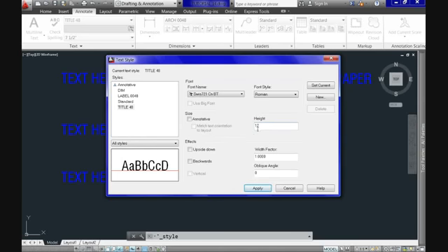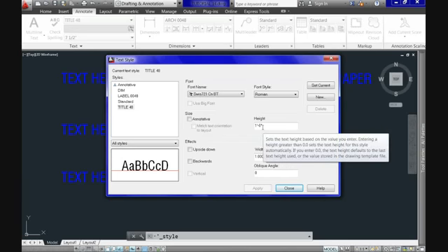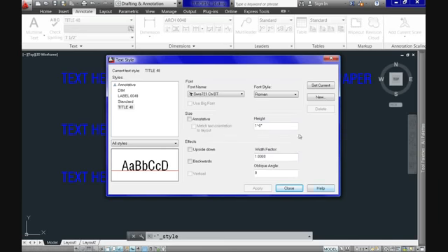So to wrap up this concept, you determine scale factors by dividing model by paper scales and then multiplying the result by the height of the annotations you want in paper space to arrive at the right height you need to specify here. Now let's visit some other features.